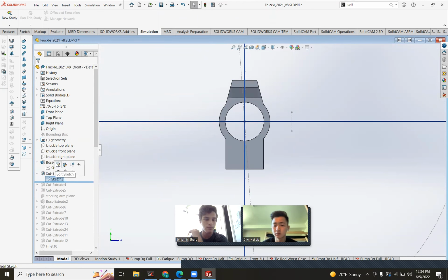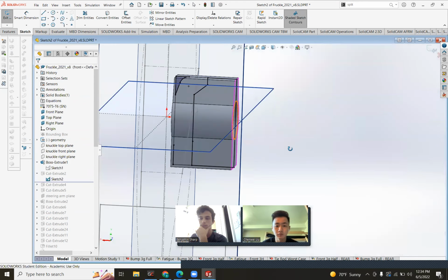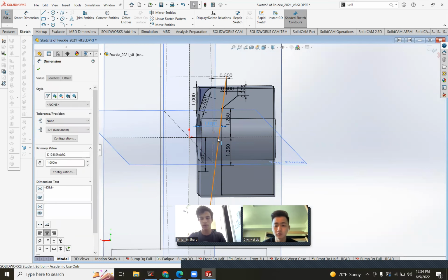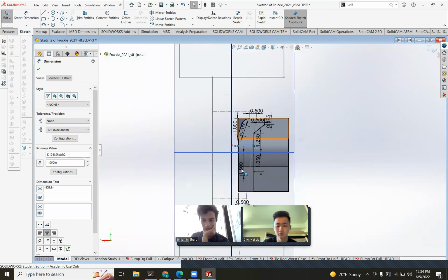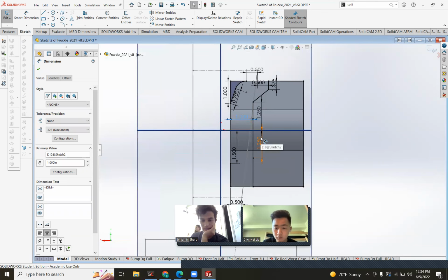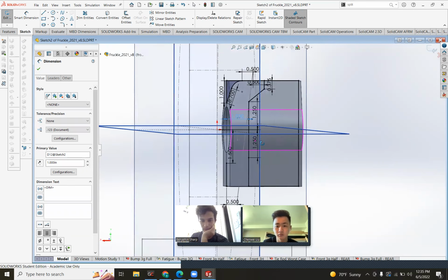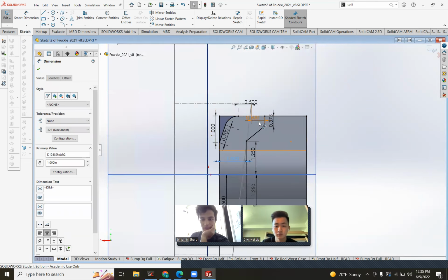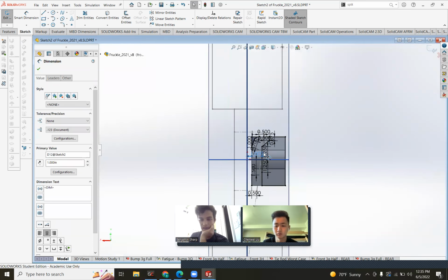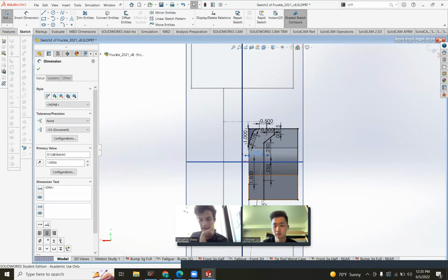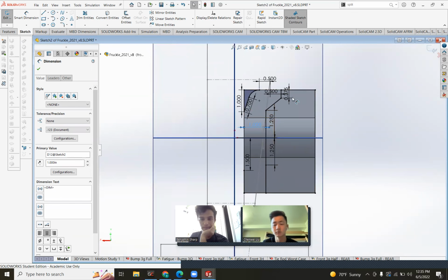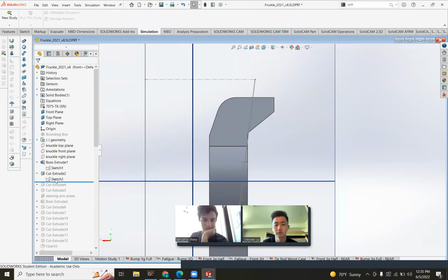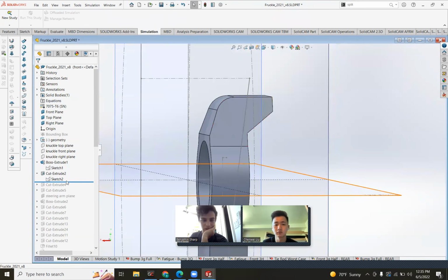This one, you have to set the total thickness, but we've almost always done 1 inch. You have to set the angle and where the material goes at the top, and you'll want to edit this when you run FEA to get it set up well. The thickness here sets the thickness of the material where the bolt goes.